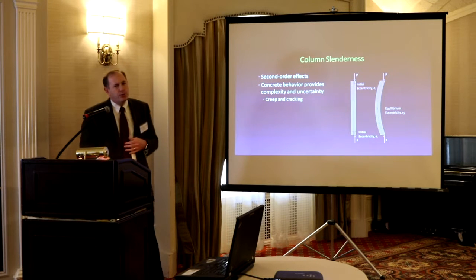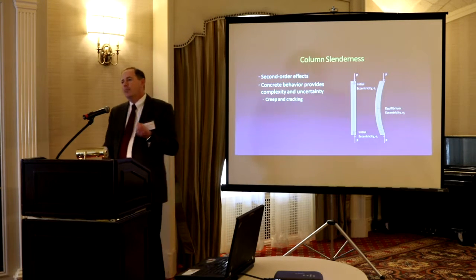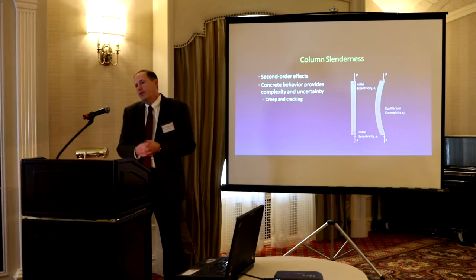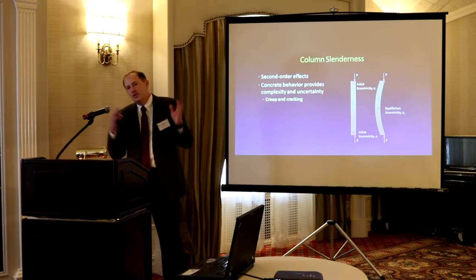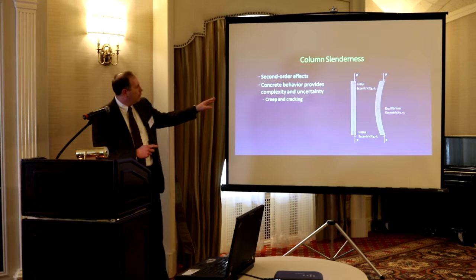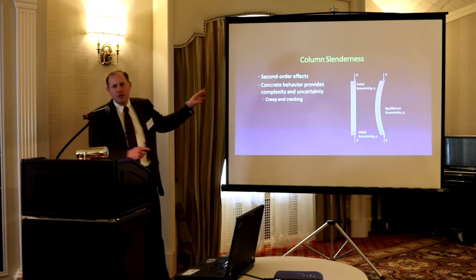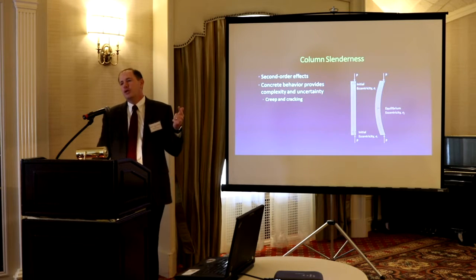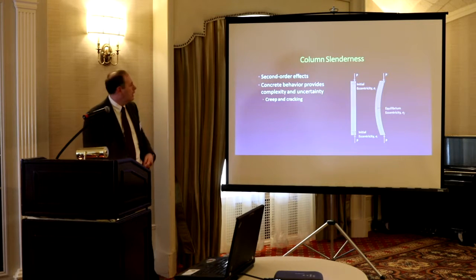So this goes back to a guy named Euler that was looking at buckling. And the equations, elastically, were very simple. When I say very simple, they're not that difficult to comprehend. The only thing that was complex for some is it added pi in there, and the students were sort of, how do you get pi inside of an equation? But the problem with concrete: with steel it's much easier because there's an E that I work with. But in concrete, we have cracking and a modulus that's not as consistent and constant.